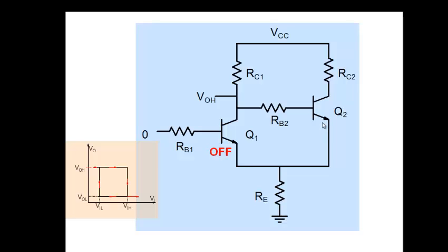And all of you know, when a transistor is on, it can be in two possible states, forward active and saturation. Now if I choose my resistors RB2 and RC2 and all that properly, what I can do is I can drive the transistor into saturation. So let's assume that our choices are correct and the transistor Q2 goes in saturation here. Okay, so it is on, we realize that, but let's assume we'll design it like that, that it goes into saturation region here. Alright, if it is in saturation region, you know that the voltage across Q2 is going to be 0.2, right?